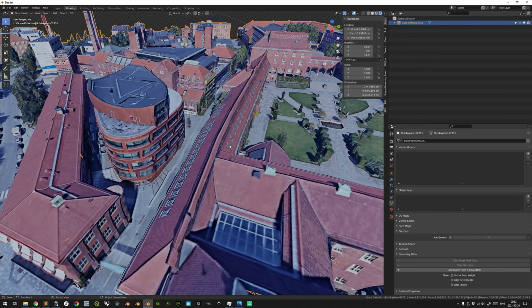Alright, and I think it was over 4,000 objects that were joined, so it would not have come as a surprise that it took close to 4 minutes to join all those objects. But now we have one object consisting of all the imported photogrammetry meshes. This is a very, very large object. It would be advisable to save the model as it is now before doing any further manipulations. Perhaps one could have done it already before the join command as well, but let's save the file.